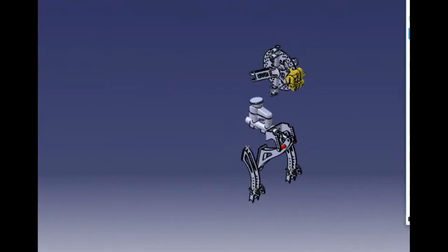Brakes are the safety components of a vehicle. The primary function of a brake is to stop the vehicle or slow it down in a certain amount of time. The efficiency of the brake depends on various factors such as the friction coefficient between the tire and ground, height of CG, frictional coefficient between disc and caliper, and the unsprung mass. In our brake system, the master cylinder and brake caliper are OEM parts. We designed our brake system around them.